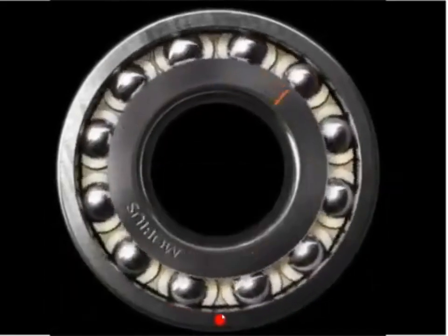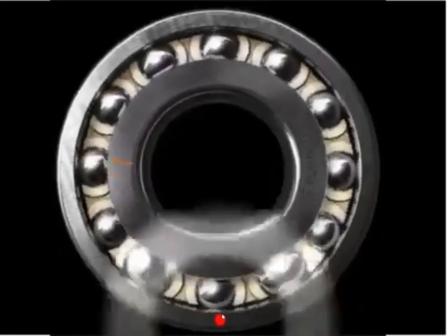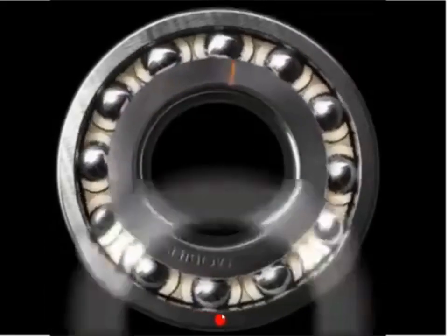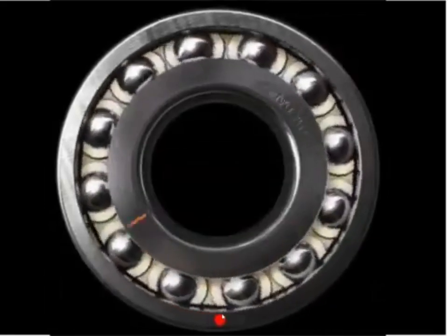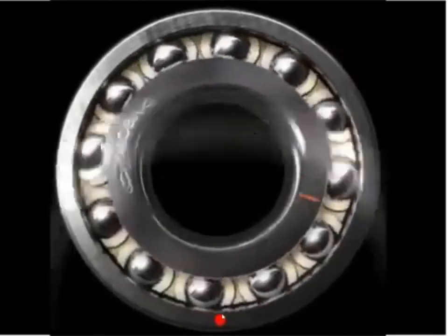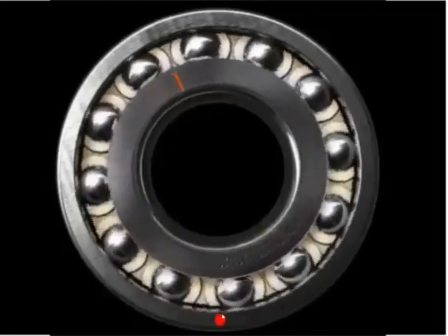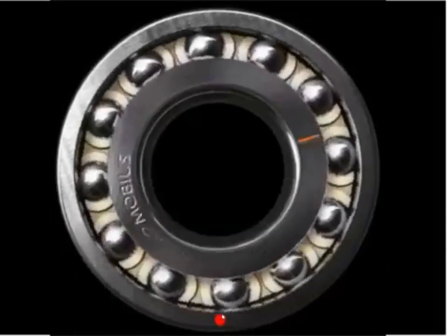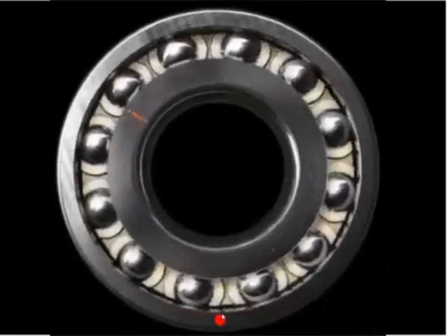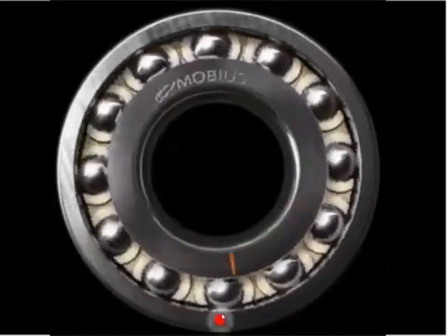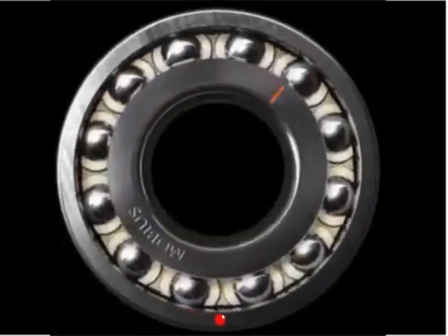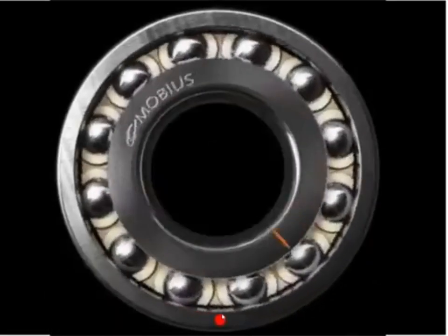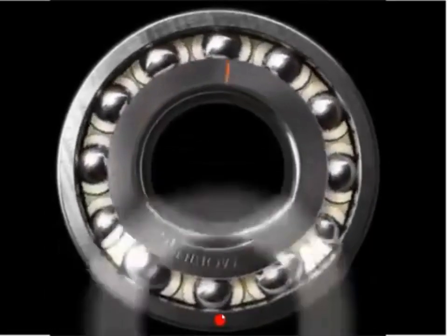Very high frequency, but the vibration analyzer can pick it up and it can provide a pattern to the vibration analyst to give them that very early warning. And then we can monitor the progress of that fault. If it's a very critical machine, perhaps high speed, high load, it could fail quite quickly, or we could get a year or more warning of a problem like this, and therefore we can plan and schedule to suit our production requirements and so on.